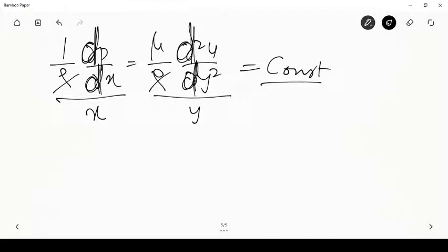Okay. So in the fully developed region, therefore, what you say is that the pressure is only a function of x, and it's a linear function of x because dp by dx has to be a constant, and the velocity is only a function of y, and since its second derivative is a constant, it actually becomes a parabola. Okay, so this is the equation that we will actually be solving.